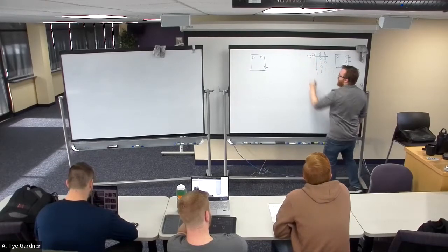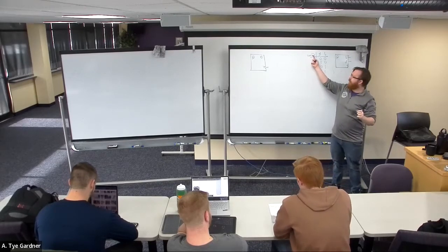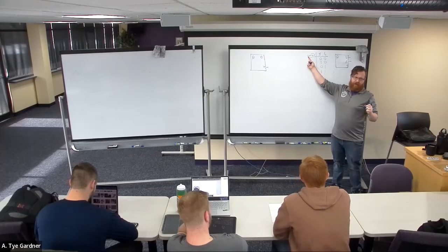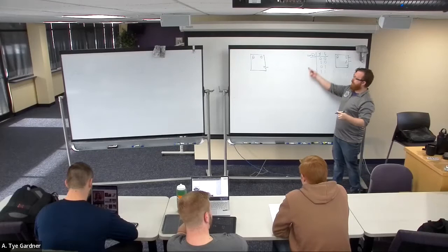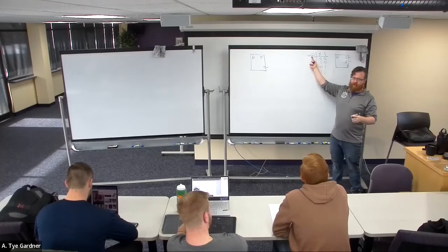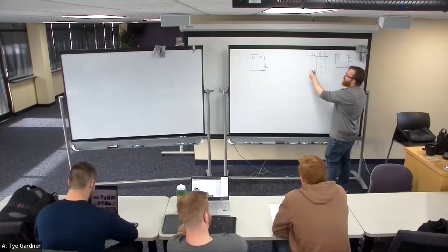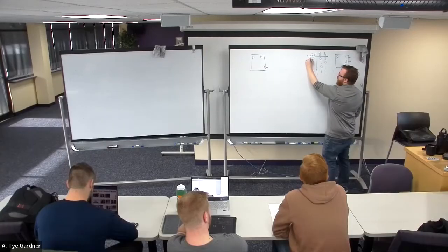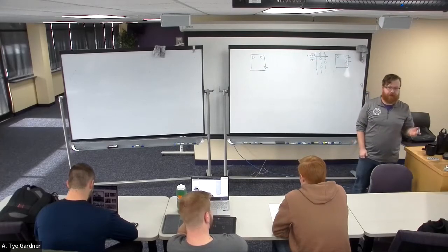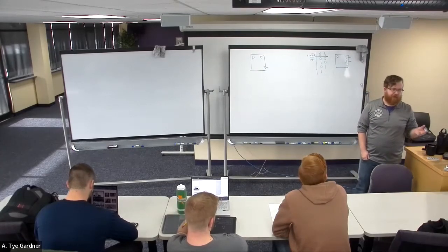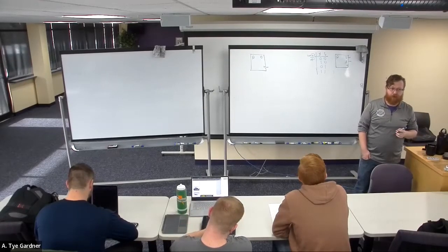We're going to talk about it in terms of time. What happens next? So this is Q at n plus 1, n being the number of Qs that had happened before. So maybe this is 100, and the next one is 101, or 0, and the next one is 1. With the JK saying 0, 0, stay the same, which is very similar to what the set reset does, which is just, if I don't set or reset, remember what you were before.